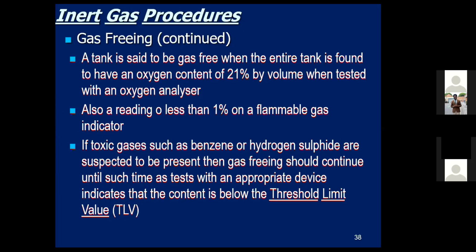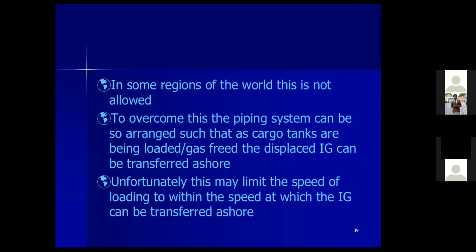And then you also have to see, for some of the Draeger tubes, how many pumps are you going to give? Some will say to test for H2S, you have to give 10 pumps. So if you are not aware of it, you give 1 pump, it's going to be a false reading, and it can lead to a catastrophic event.